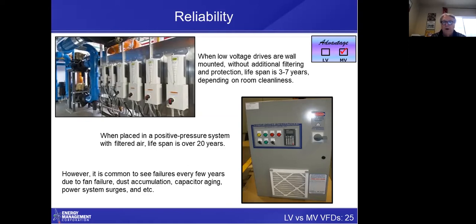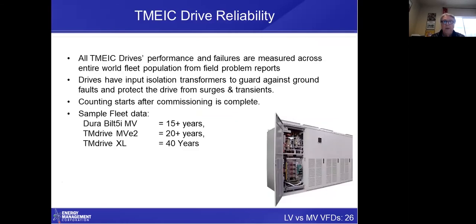If you look at the drive on the lower right, this is more of an industrial high quality drive in which we put it in a metal enclosure and we have forced filtered ventilation so that it keeps everything inside very clean. You should get 20 years out of this drive. But I'm not saying 20 years of mean time between failure, I'm saying 20 years lifespan. The mean time between failure is not going to approach 20 years regardless of what supplier you use.